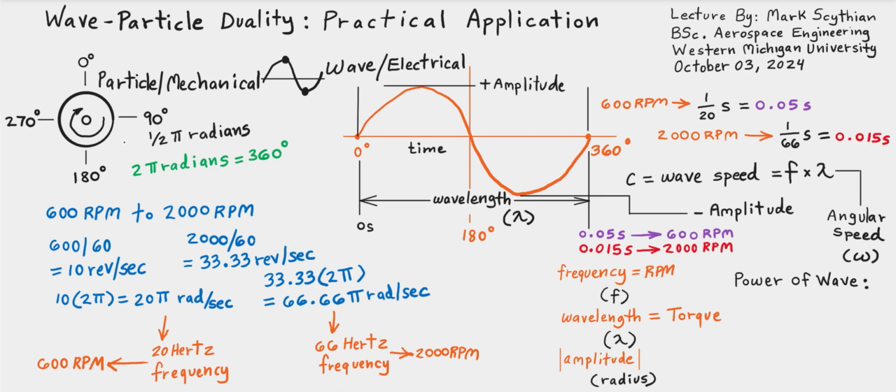So this is very common with wheel speed sensors on cars and airplanes, so that all four wheels can rotate at the same speed to prevent skids. Typically, when the slip and skid differential is exceeded, in other words, you're making too sharp a turn at too high a speed, one of the wheels is going to spin a lot faster.